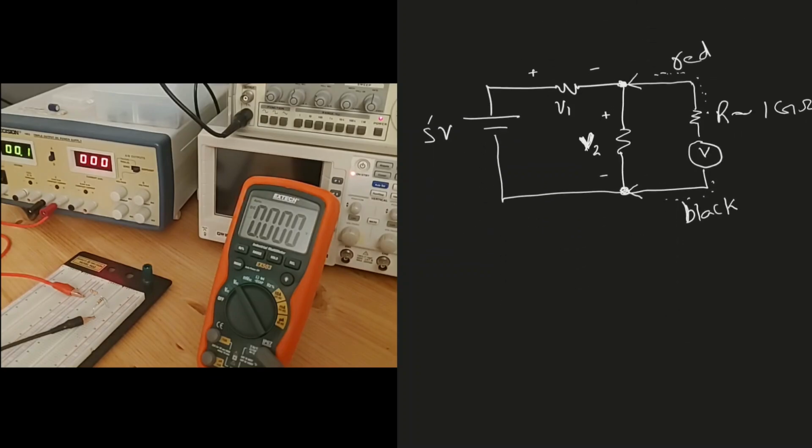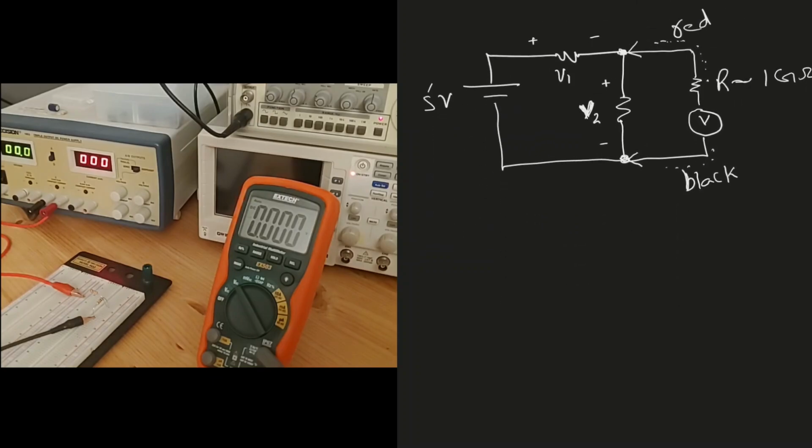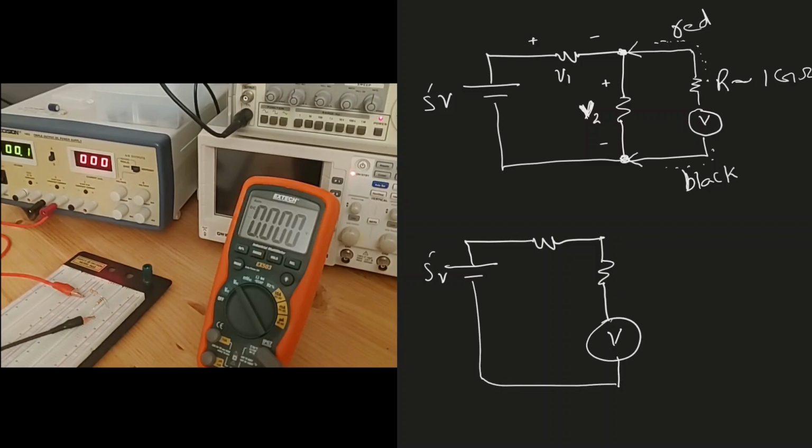Now, this introduction of the voltmeter, you should be able to now see what will happen. For example, if I have this DC power supply, 5 volts and V2, and if I put the meter over here in this way, right? If I do this, now what will happen? Now you can see that the voltmeter has a very high resistance in series, okay? It's like an open circuit. So this circuit is actually this way, that you have a power supply and one resistor and another resistor and then a huge resistor.